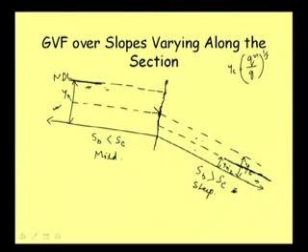Here it is subcritical, here it is supercritical. So, at this point it will change and it is moving like this, and this profile will meet the critical depth line normally. It will be moving like this, gradually rising, and then it is meeting this NDL line asymptotically.